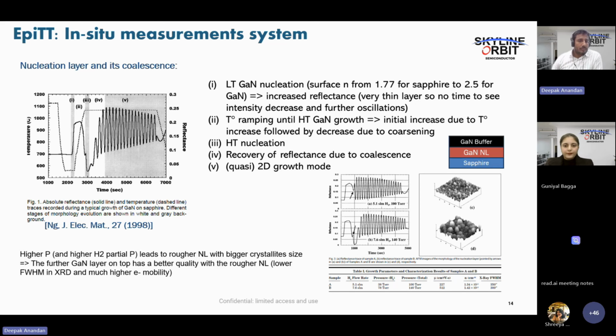So here, in our gallium nitride system, we are using a 633 nm laser, which can be sent inside the chamber, and it will be reflected from the substrate, and the reflected signal will be transferred to the analyzer spectrometer. Here you can see two different path signals.